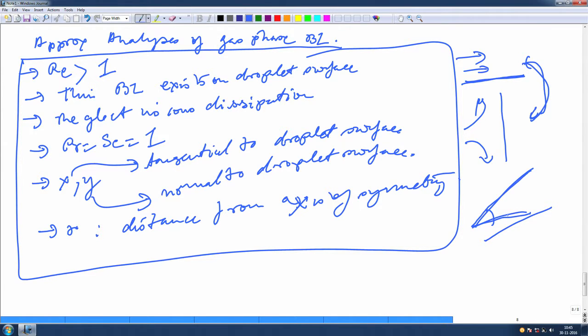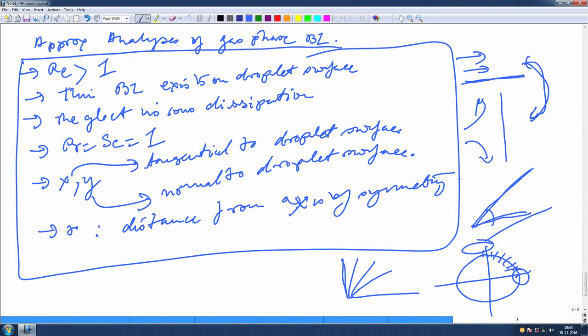Okay. So, Falkner-Skan is applicable for any wedge, whatever the magnitude of that wedge is. When the wedge becomes 90 degrees, it becomes what we call Hiemenz or stagnation flow. When it becomes 0, it becomes like a flat plate boundary layer. So, what we are trying to say here is that a droplet can be resolved in pieces, and locally it can be made to approach a situation like this. One way it can be like a flat plate, one way it can be like a stagnation point, and in between the curvature changes. So, it is almost like these wedges.